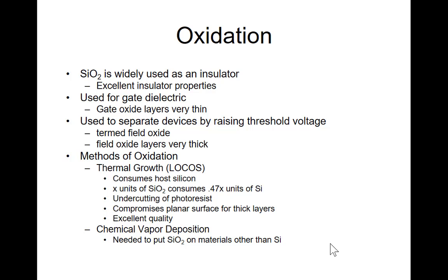Now, if you have the silicon surface at the original height, after the top layer combines with oxygen, the surface height will actually become higher because silicon dioxide is larger than silicon. When it combines, the molecules become larger, so it grows upwards. That's why you call it growth. And for growth, you can grow thin oxide and thick oxide. Thin oxide is like the oxide underneath your gate.